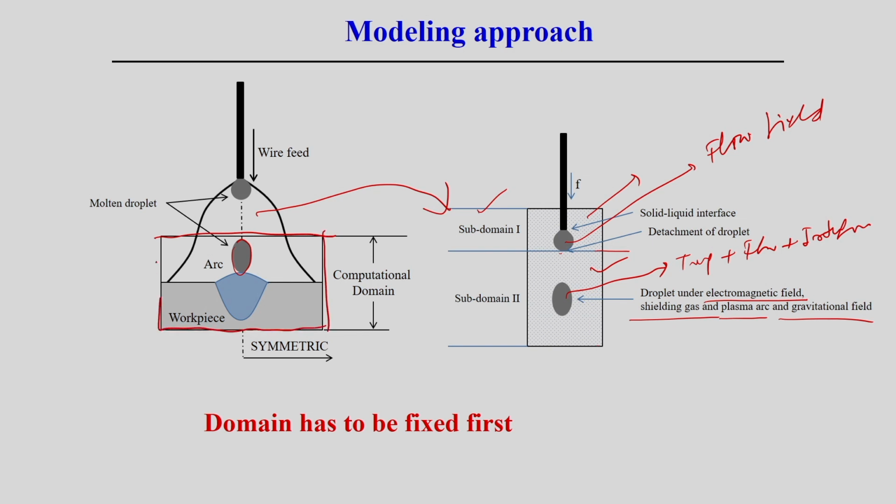the computational domain, and within this computational domain we can do the analysis of the temperature distribution as well as the flow field and free surface field, but it is associated only with the metallic domain, only the metallic component part. So, we can exclude the analysis of the gas and the arc here. But the shielding gas distribution, its flow field, and even arc pressure, basically arc formation, the domain of the arc, can be done separately. That is a different domain, apart from the metallic domain.